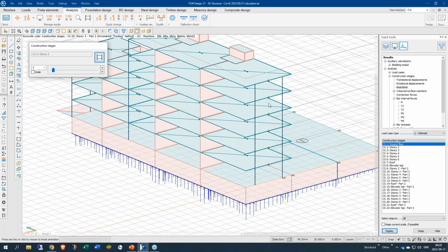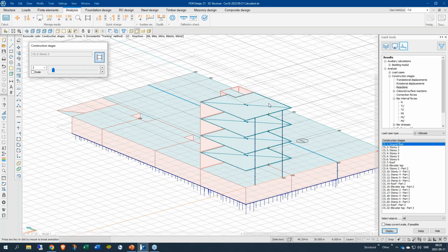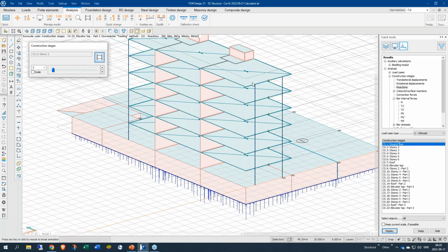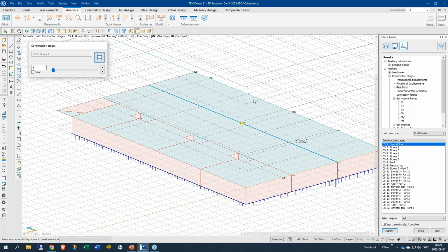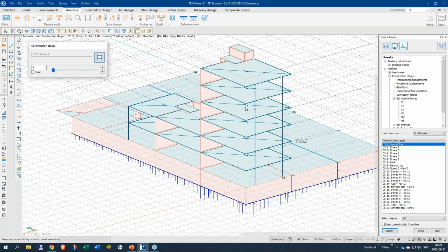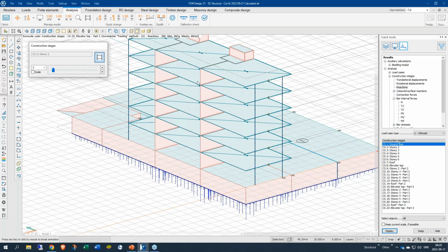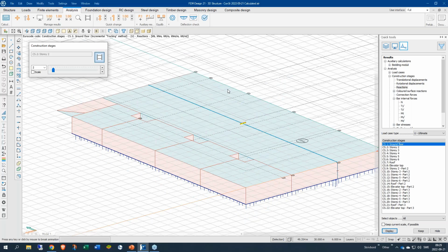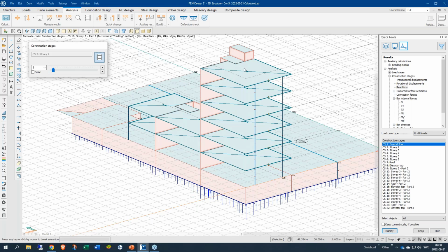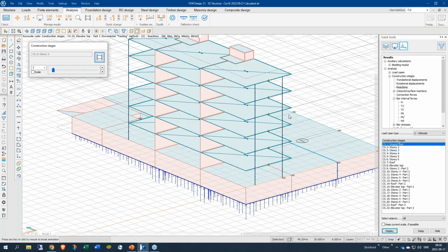And this type of structures being built like this, it's giving much better results. Otherwise, there will be redistribution of the loads, and there might actually be tension in some columns here, just because of how the loads are carrying down when we are just applying all the loads at the same time, compared to when we start to divide the structure up.